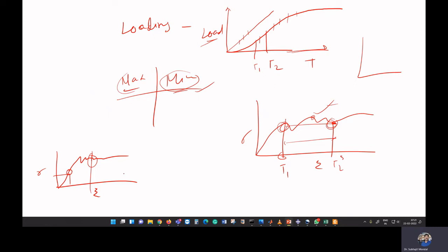Now the thing is, how much maximum load you can provide also depends upon your stress strain behavior. You should have some idea of the stress strain behavior, or what is the maximum deflection it can cause during the failure. So here you have to see how much strain is occurring during the failure, and from there you can calculate what is the maximum displacement that can occur.